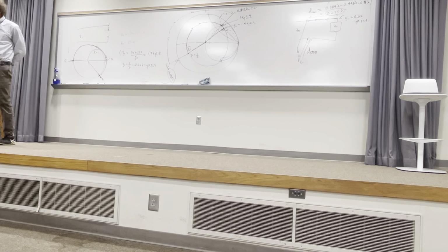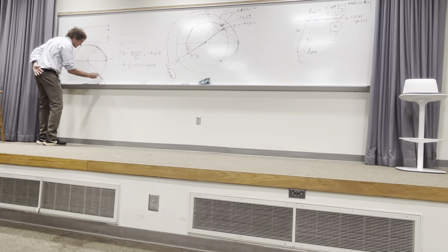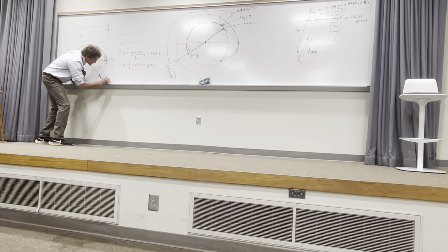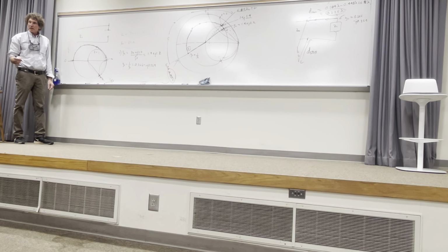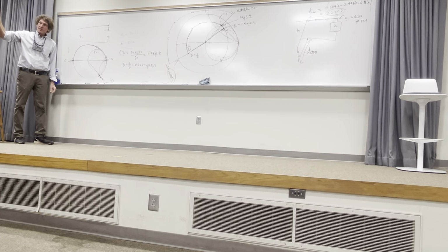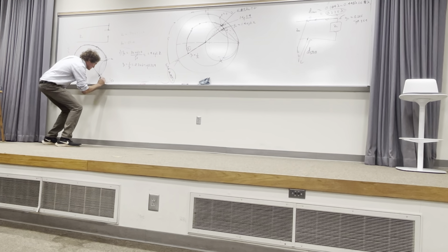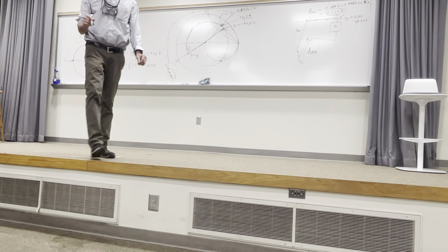Make sure you go from the center right to the value where that 1.9 trajectory intersects here. You've got to go straight through here. And then you're going to look here and you're going to see something wavelengths towards generator. You'll have to give me that value. 0.315. Say that again? 0.315. Anybody confirm that? 0.315? Okay. No, I got 0.325. We got 0.325, 0.327, 0.325. It's all in there.